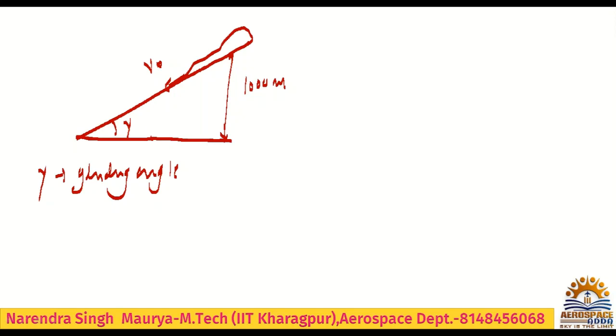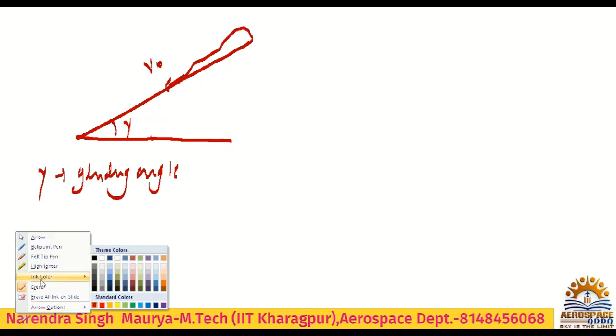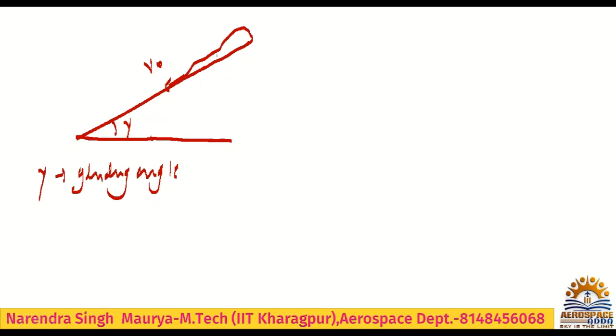At some hill point or some altitude, which is nothing but 1000 meters. So how to connect this problem? See, it's very simple. Better I will draw another triangle. Here I just want to resolve the components so we can proceed. Anyway, so we can say this is v infinity. So obviously this glider will have a weight because mass is given.